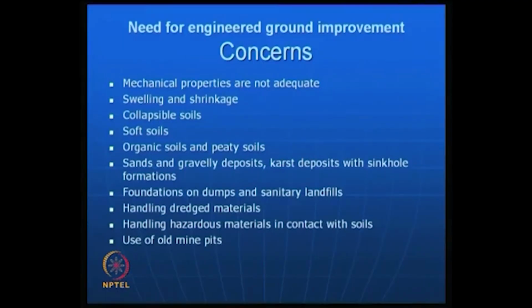So, these hazardous materials need to be really immobilized, in the sense they should not move from one place to another. So, we have some techniques where you try to add some additives, so that the permeability of the whole soil is very low, and the movement of these hazardous materials, whether in a solid form or liquid form, is minimum.